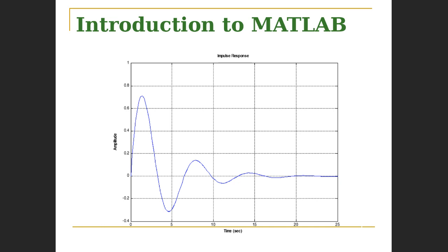Yes? So you hit that spring almost like a suspension hitting a pothole, and if it doesn't have good shock absorbance, shock dashpot damping constant, then you're going to have a lot of vibration happening, and it takes quite a while. So imagine if you hit a pothole in a vehicle, and 20 seconds after hitting that pothole before the vehicle comes back to any sense of steady state. I'm using the term steady state here, but the term of normal movement, okay? That's exactly what we're doing here at MATLAB. We derive our system, put into MATLAB, and we see what happens.